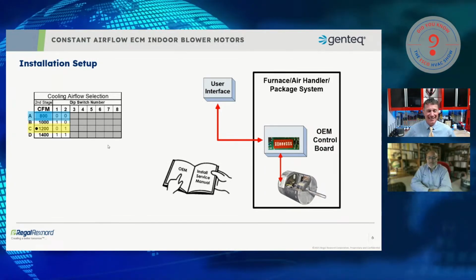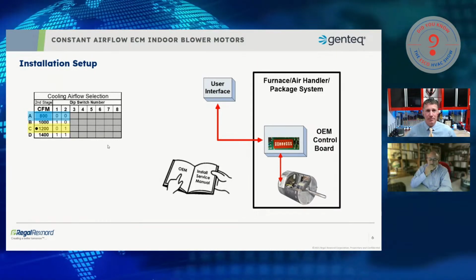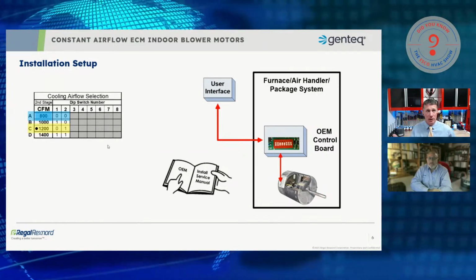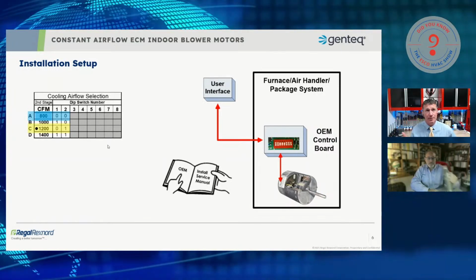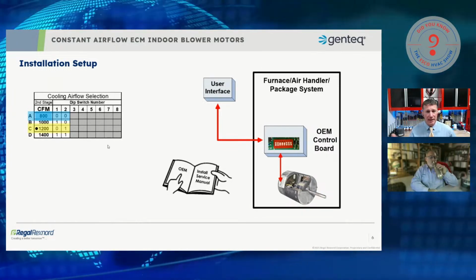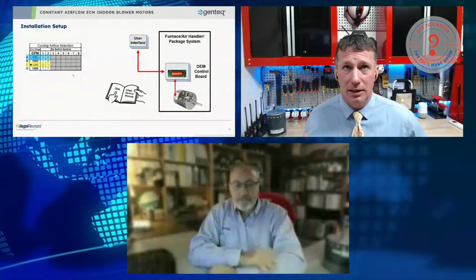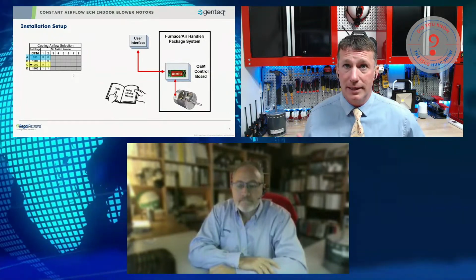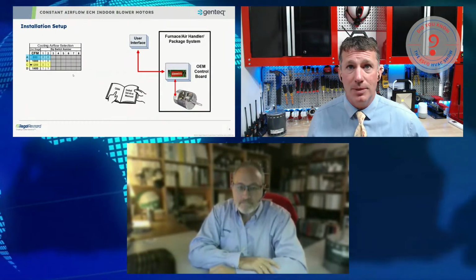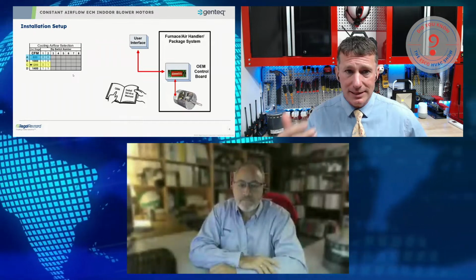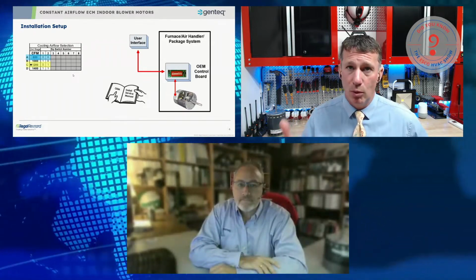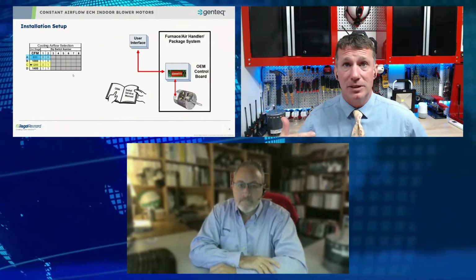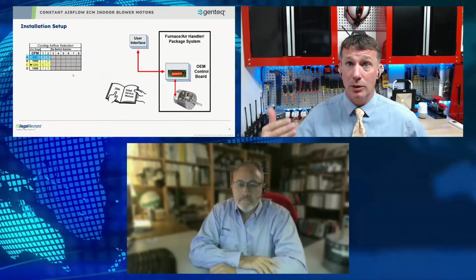And unfortunately, it's a very common mistake to not be commissioned properly. We see it all the time, where in that exact case, the call would be, "Hey, I've got blower fault codes on this communicating thermostat." And you go, "Well, what is the blower trying to do?" That's what it's telling you. It's trying to do something. And many times it's exceeding its temperature because it's trying to move more air than it is designed. So the static pressure, and if we had an 800 CFM duct design and we're trying to push 1200 through it, we all know what's going to happen.